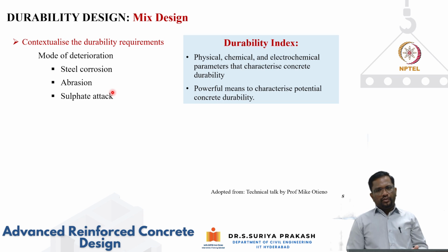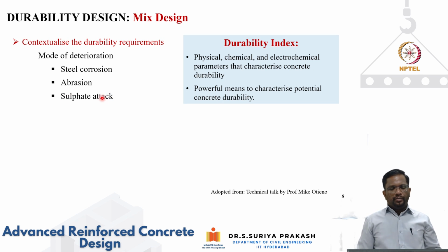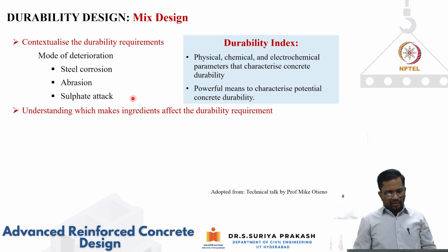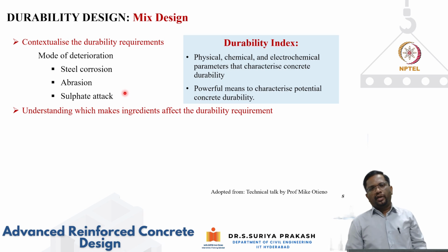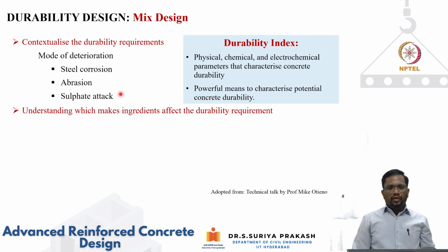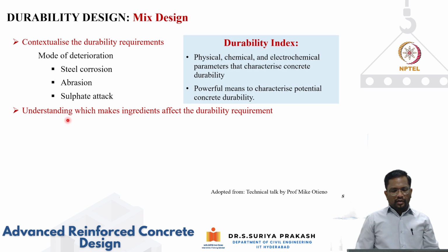And you know that the foundation, if it is sitting on a sulfate rich soil, then sulfate attack will be a major deterioration mechanism. So we need to clearly understand what kind of deterioration that particular structure will be subjected to when it is built in a particular environment. And the understanding also of what ingredients affect the durability requirements.